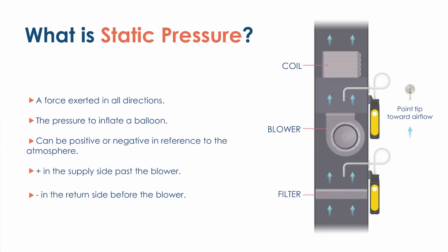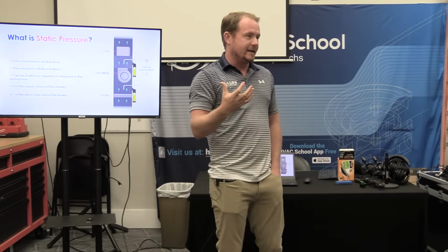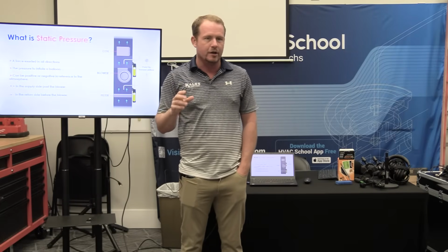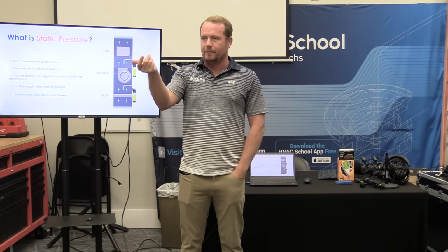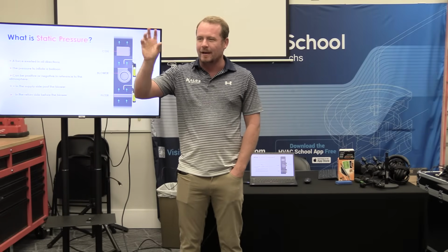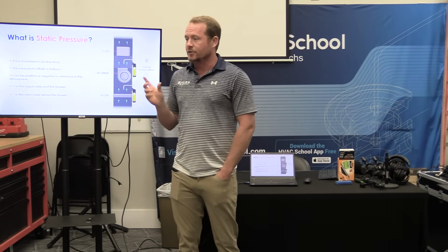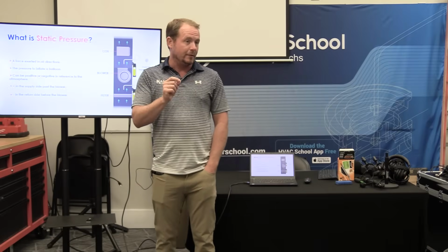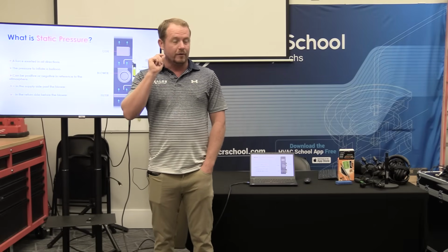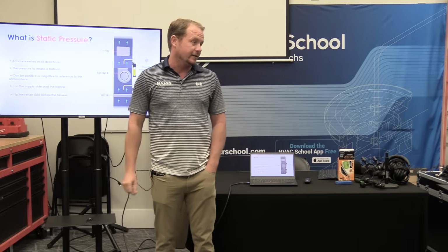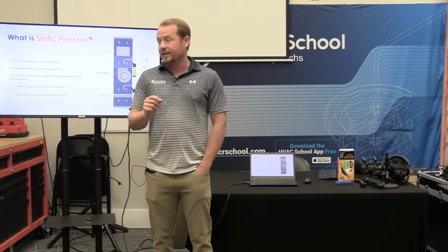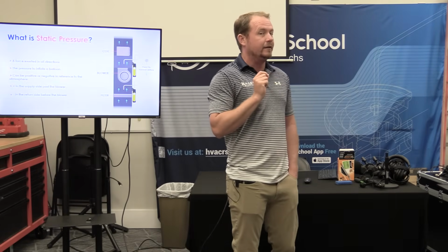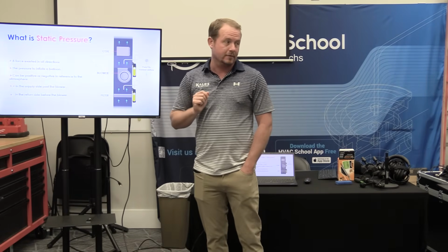Now, what we've learned in residential systems is that the positioning of our static pressure probe really isn't that critical. The way you can know is you take a pressure reading and spin that probe all the way around, and it doesn't make a massive difference in most cases. Which is why, in some cases, people have taken to using things like ball needles, so you can drill a much smaller hole and place the ball needle in. Obviously, you couldn't do that in ductboard because it's not going to be long enough. But when you're measuring within a cabinet, it's easier to make a tiny hole and place a ball needle in than it is to use a static pressure tip.